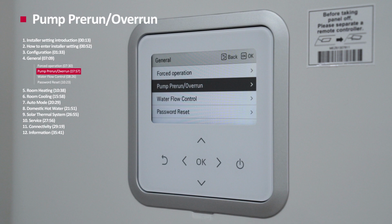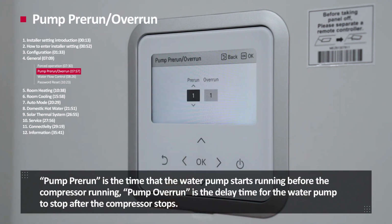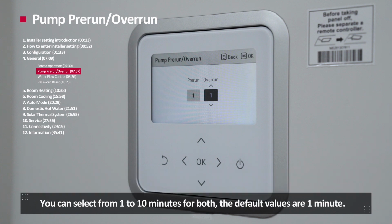Pump pre-run, overrun. Pump pre-run, overrun sets the delay time of the starting and stopping of the water pump operation. Pump pre-run is the time the water pump starts running before the compressor running. Pump overrun is the delay time for the water pump to stop after the compressor stops. You can select from 1 to 10 minutes for both. The default values are 1 minute.